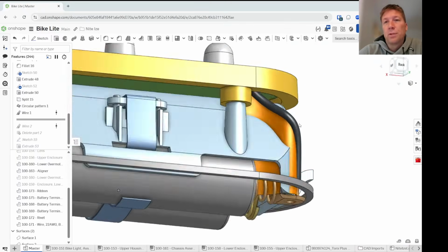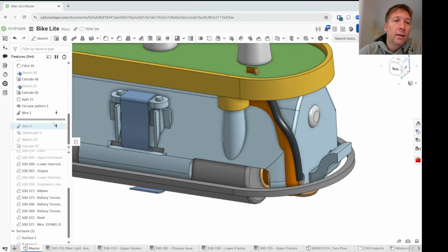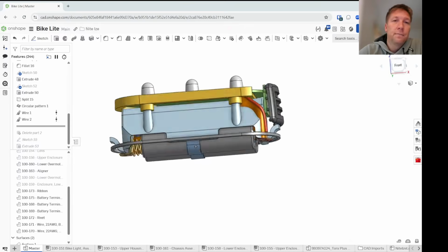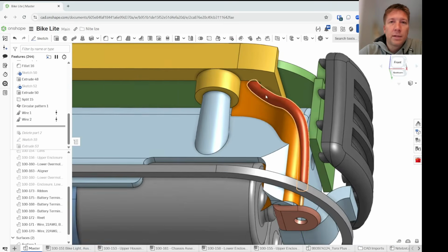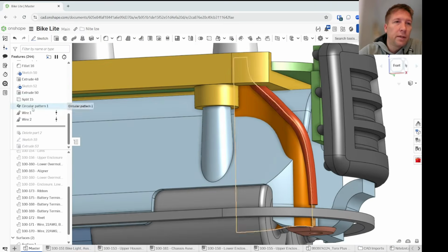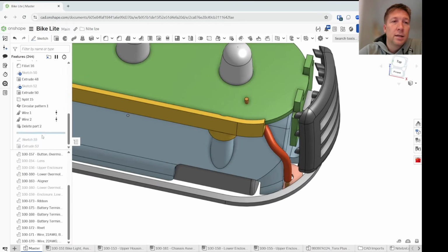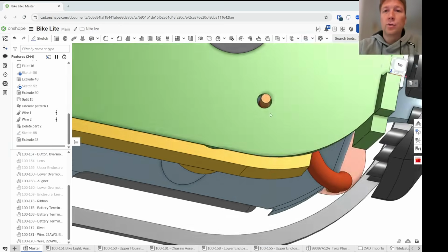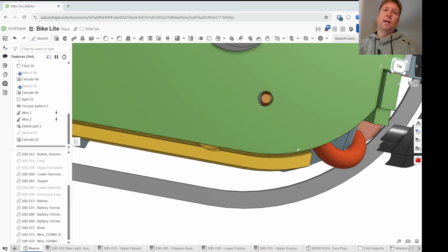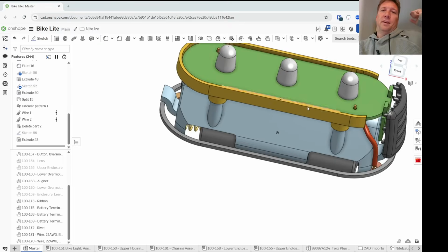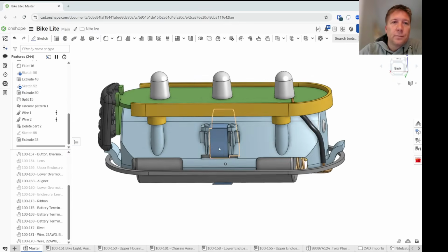Like it's for visualization purposes only, but that allows me to tuck that wire through that gap. And I can do the other one with the other side. This one I'm going to do as a red wire. Interferes a little bit with the chassis right there. In real life it doesn't, but I don't need to worry about that for right now. And then I delete the two surfaces and I'm just left with the wires. And I can go ahead and do a cut extrude from where those wires penetrate the board to create the hole that will then be fed to my electrical engineering team to build that circuit board.